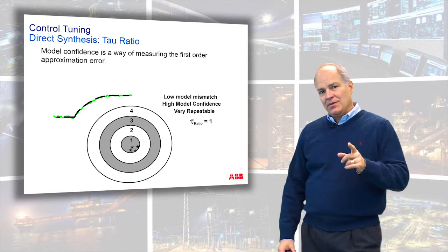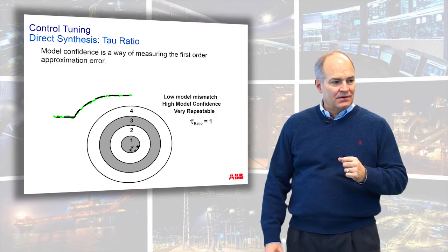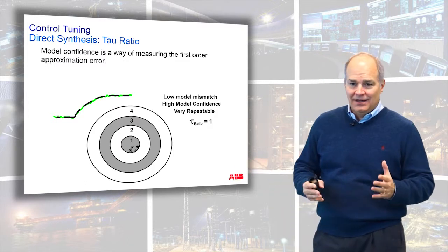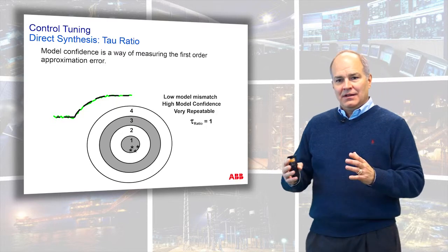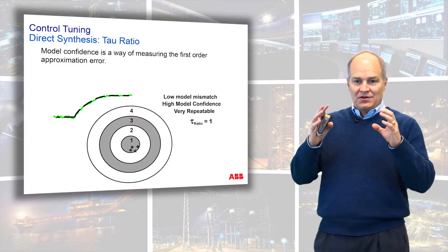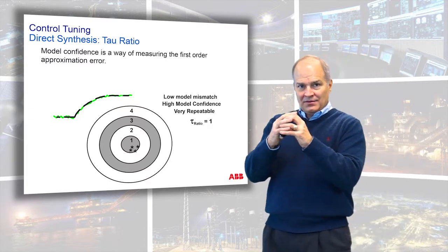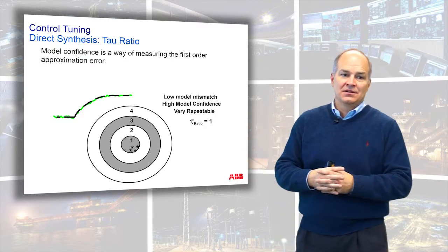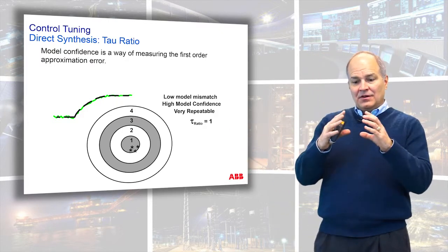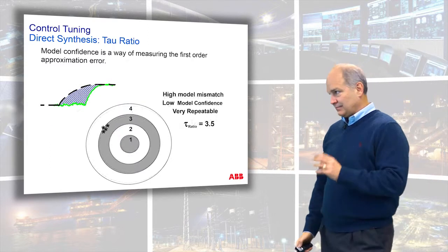But you have to worry about what happens. What do you think happens when valves wear or instruments wear? They tend to slow down. So as they slow down, you need to adjust your model. So if you have your controller tuned very aggressive and over time it moves out of the window, oscillations occur. So it's better to set your target just a little bigger so that you allow your process to wiggle and you won't get called in the middle of the night.